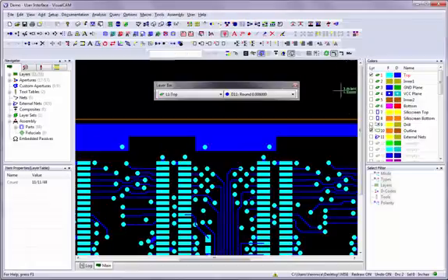Tagging layer types is necessary for many commands in VisualCAM. When you are working with an intelligent file like IPC2581 or ODB++, the layer types will already be set on import. When working with files like Gerber, you need to manually assign the correct layer type to each layer prior to running an analysis or making changes to your data.